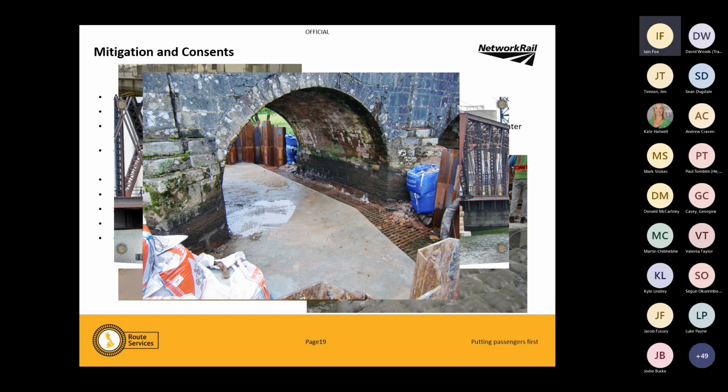We do require consent for permanent and temporary works. The temporary works one's generally harder. Permanent works, the permanent state is normally acceptable. It's the methodology of how we get to that point that is usually the tricky one. No barrier to fish migration is a biggie at the moment. A lot of the works we do are on rivers where salmon can get up to spawn, so we're not allowed in within fish spawning season at all.